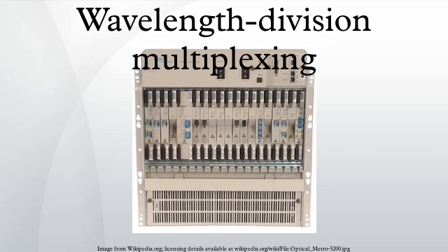Enhanced WDM. Cisco's Enhanced WDM system combines 1 GB coarse wave-division multiplexing connections using SFPs and GBICs with 10 GB dense wave-division multiplexing connections using XENPAK, X2, or XFP DWDM modules. These DWDM connections can either be passive or boosted to allow a longer range for the connection.